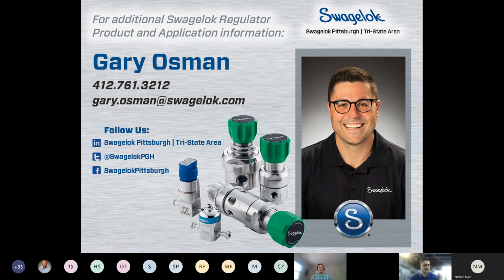It's really made to relieve the excess pressure from changing set points, not a system overpressure. So the flow capacity is not there, and the sensitivity isn't what you would require from a relief device. While they function very similarly, we never recommend to substitute a self vent for a dedicated relief device.